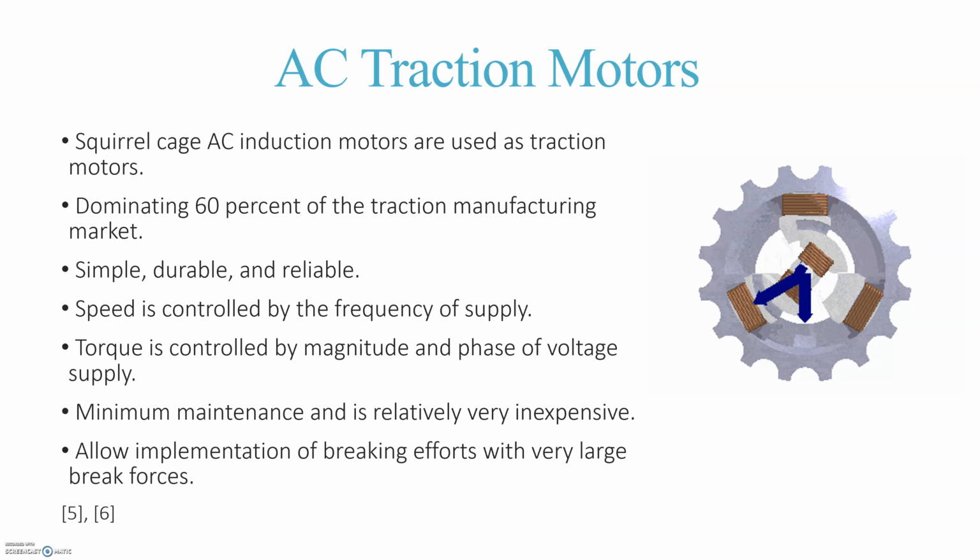Since the induction motor has no electrical connection between the stator and the rotor, there are no brushes and commutator, and they allow implementation of braking efforts with very large brake forces, recovering more energy when used in regenerative braking mode and eliminating the need and consequent cost of the braking mechanisms.